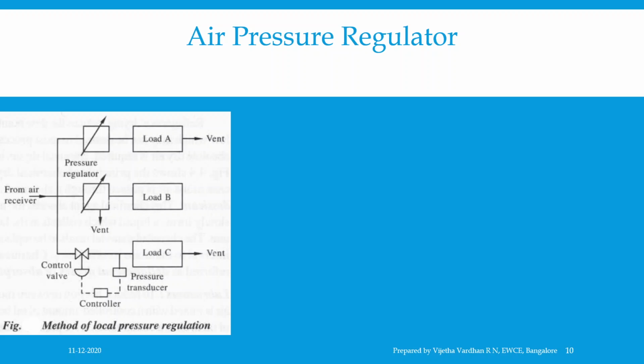Method 1. In this method, the pressure regulator simply restricts the airflow to the load. This type of regulator has two ports and requires some minimum flow to operate. If used with a dead end load which draws no air, the pressure rises to the main manifold pressure. Such regulators, in which the air must pass through the load, are called non-relieving regulators.